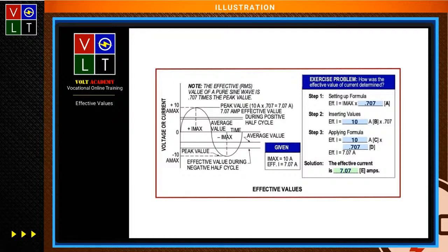Gotcha. Now, as I look in the formula, what is I? I, in the formula, is the effective value, and IM is the maximum. That's why I gave that formula. If the maximum current has a value of 1, then the RMS is equal to 0.707. And that's determined by I equals 1 divided by Z, which is the impedance, times 1.414. And that will get you 0.707.